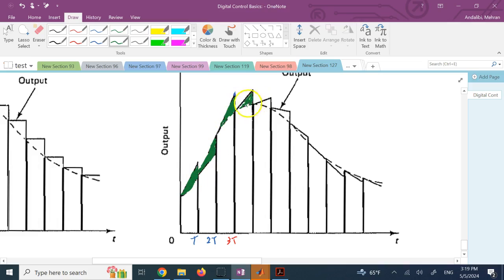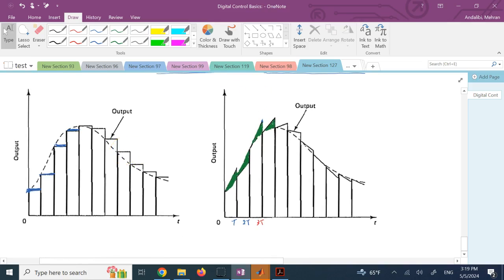If you look at their size and their shape, you see they are not as bad as the zero order hold. Okay, so now for zero order hold, these are the regions of deviation, and you see they are quite a bit bigger. So overall, keeping a higher order hold makes the approximation better, but at some expense.